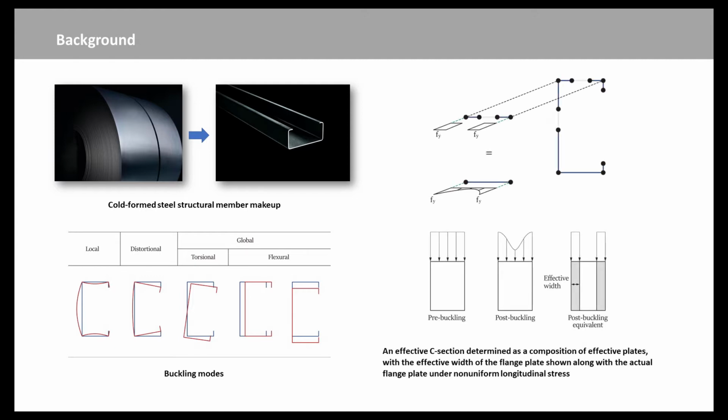Currently, two basic design methods for cold-formed steel members are formally available in design specifications in Europe and North America: the traditional effective width method and the direct strength method. The essential idea of the effective width method is that local plate buckling leads to reductions in the effectiveness of the plates that comprise a cross-section. The effective width of each flat element of the cross-section has to be determined. As a result, each element is considered separately, ignoring the rotational restraints provided by the adjacent elements.